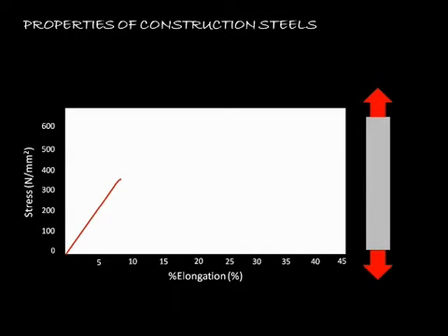Another load increase sees the stress-strain plot begin to curve. It is said to be behaving elastic-plastic, and is an indication that the steel bar is becoming permanently deformed. Where the plot begins to curve is called the limit of proportionality. At the end of this curved section is the yield point.